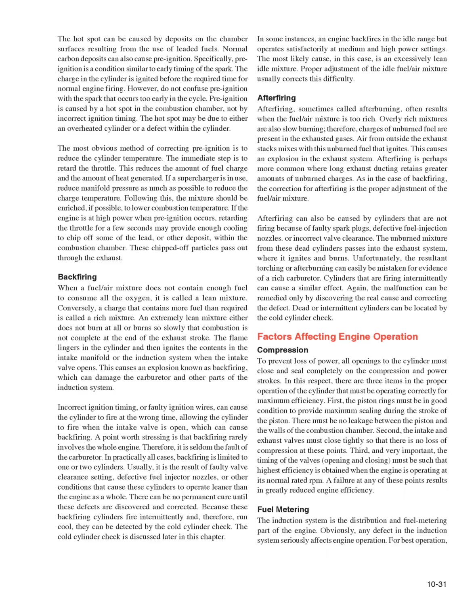The hot spot can be caused by deposits on the chamber surfaces resulting from the use of leaded fuels. Normal carbon deposits can also cause pre-ignition. Specifically, pre-ignition is a condition similar to early timing of the spark. The charge in the cylinder is ignited before the required time for normal engine firing.